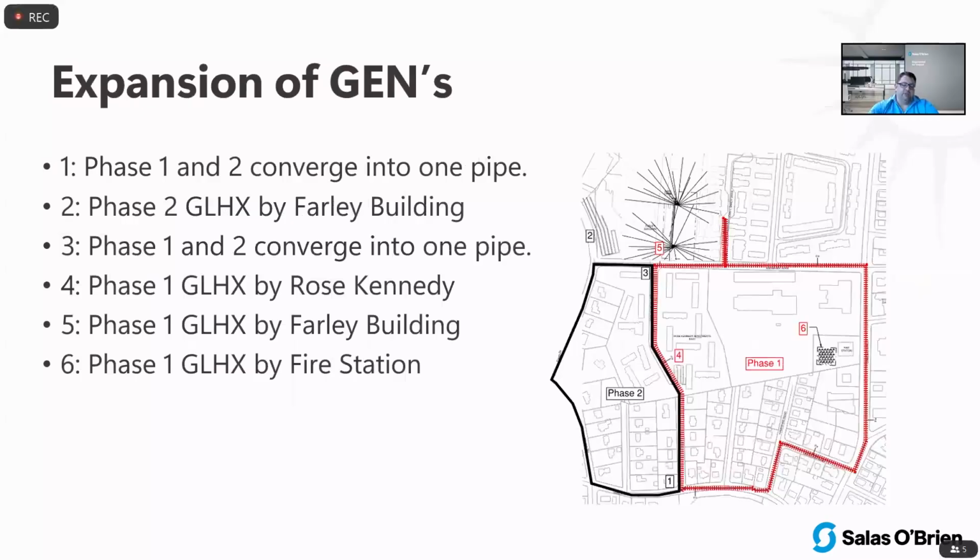And then the last thing I would just say, when designing these systems, we really have to consider the expansion of these systems in the future and how are we doing that? For instance, one of the projects we worked on with HEET actually in Framingham, they had put some T's and some valves on the piping thinking about expansion. And then as we got into designing the expansion, we realized that that really wasn't done in a way that could do it the most optimized way for hydraulics and for energy sharing.